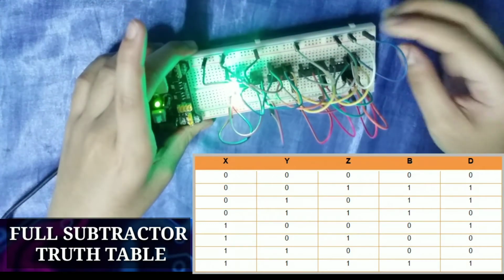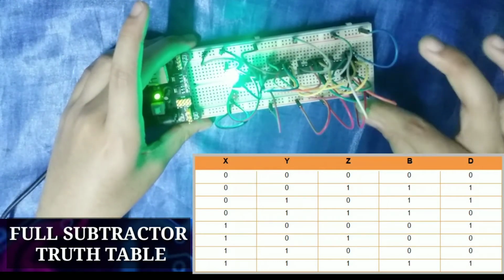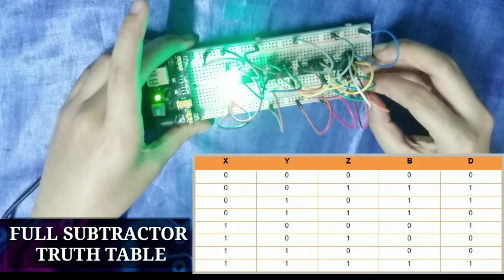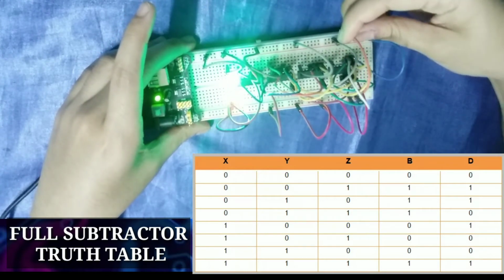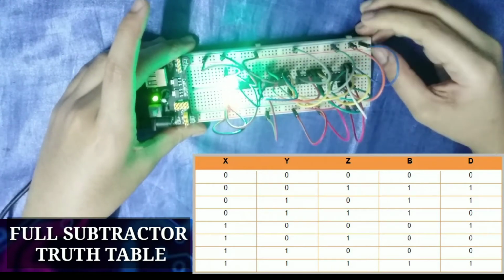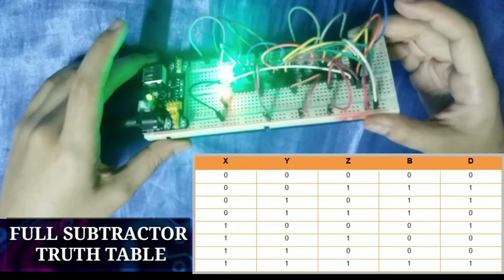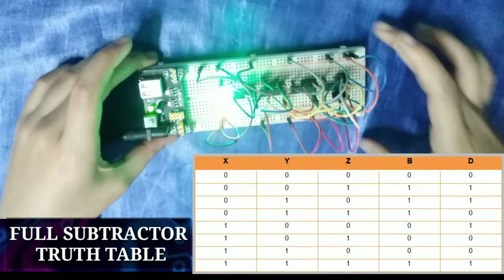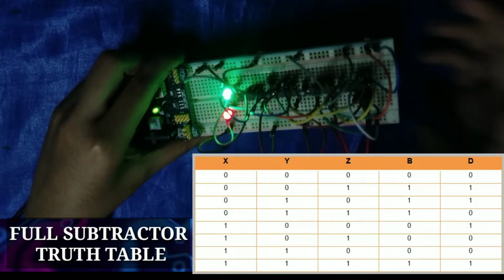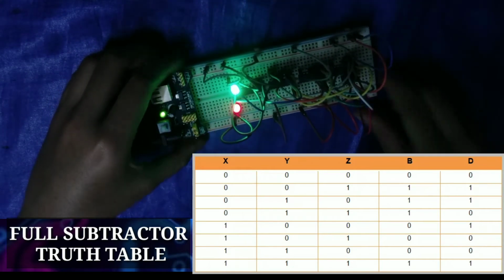Now, if only input Y, or only the white wire, is connected to the VCC, or at logic 1, and both of the other inputs are 0, connected here on the other end, as you can see, both of the D and B outputs, or the green and the red LED, are both turned on.